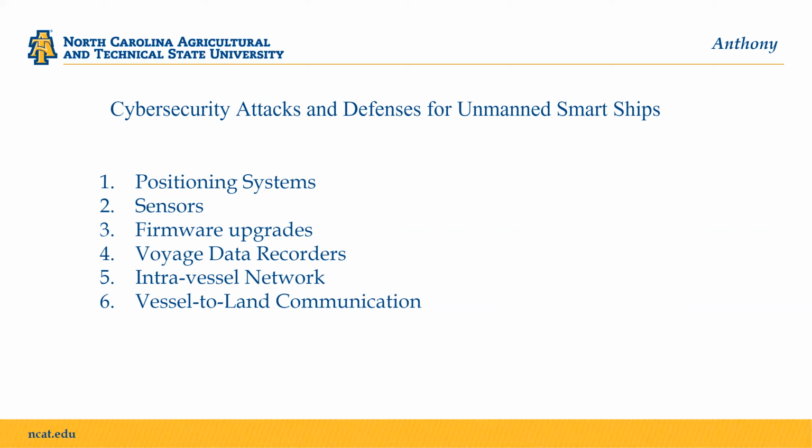And the next attack is intra-vessel networks. Traditional backbone ship area networks, or SANs, are mostly wired by design to meet reliability requirements. For communication in wired networks, maritime standards call for the use of the controller area network, or the CAN bus technology, which has been developed for the automotive industry, in which CAN bus has simplified the addition of new modules and equipment without affecting existing cabled installations or networks. The CAN bus in a ship connects, controls, and monitors shipboard electronic equipment, instruments, sensors, and actuators.